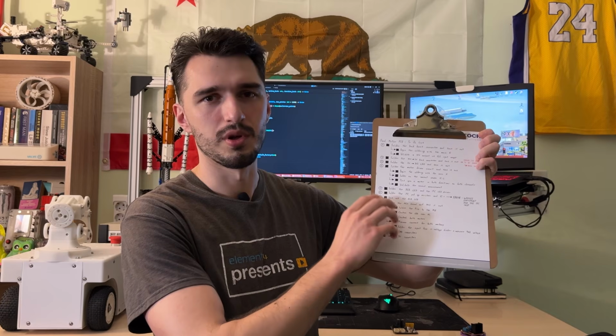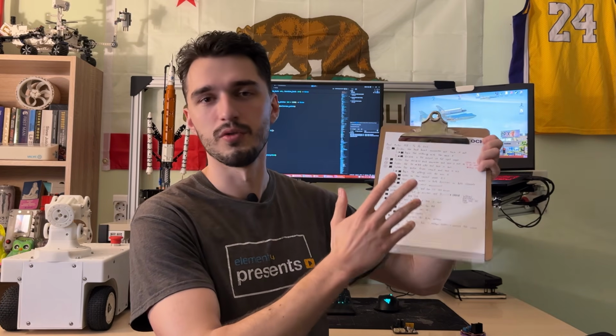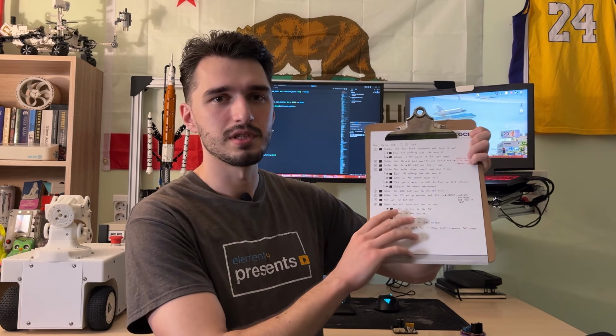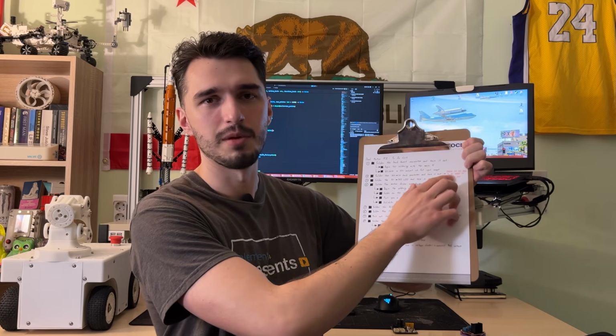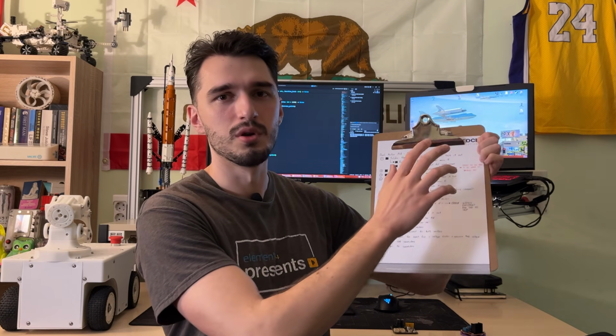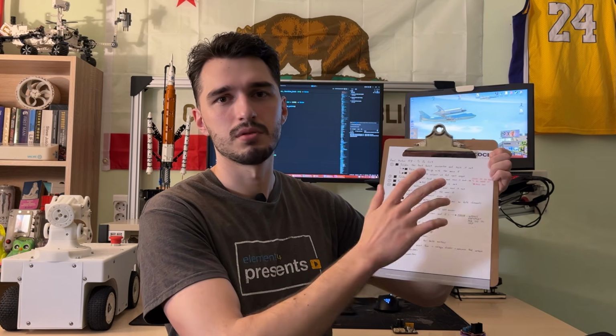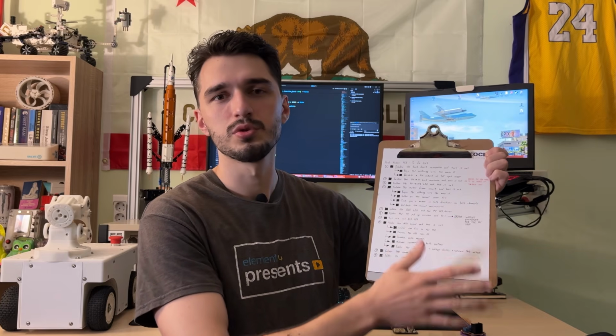You won't always follow it step by step, you won't do all of the tests always, of course. But it was a really nice way for me to write down, for example, a wrong footprint and also a pin that was tied not in the way it was supposed to, and it was burning out a chip, as you will see in the system requirements update in the next clip.